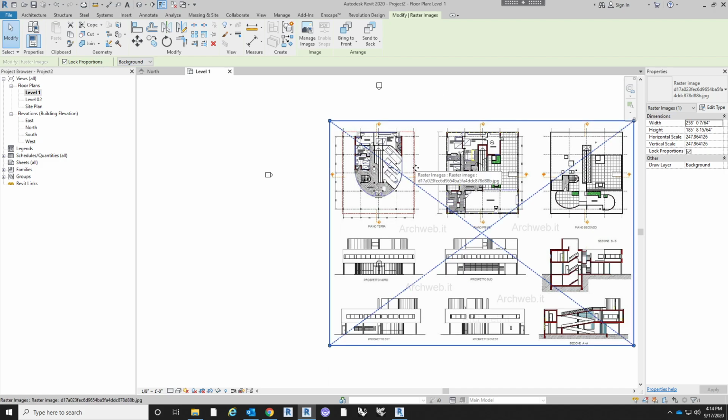To do that, select the photo by clicking it, then go up to the Modify tab, and directly to the right of the Scale button is the pin. Select that, and then you can't move or shift it until you unpin it. To unpin it, either click the pin that comes up when you select it, or go up to the Modify tab and select Unpin.